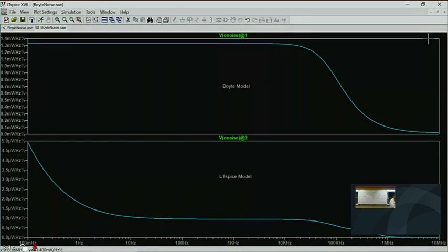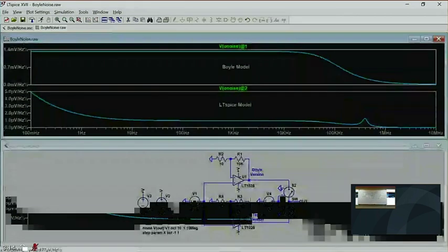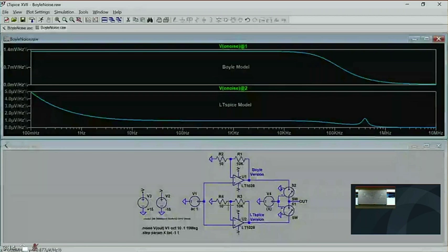That's all true. But an LT1028 doesn't have a gain of 1,000 at 10 megahertz. So the voltage noise test fixture doesn't work at that frequency. It's just that this circuit can't test the noise there, and that's why. This is the correct simulation result. It's just you can't see this. Then there's this little mountain of noise here.